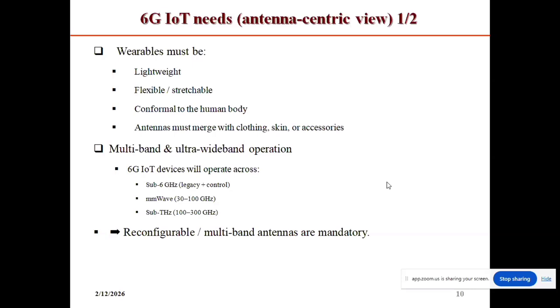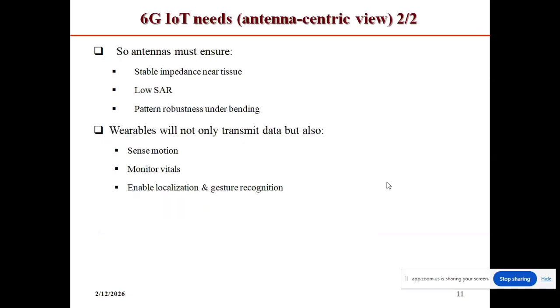The same antenna should not be used only for a single frequency; it can operate at multiple frequencies. That is also required for this application. The antenna should be reconfigurable, and multi-band antennas are mandatory for these applications. The antenna must ensure stable impedance on tissue, low SAR, and pattern robustness. Wearables will not only transmit data, but can also sense motion, monitor vitals, and enable local processing. These are some things about wearable antennas.